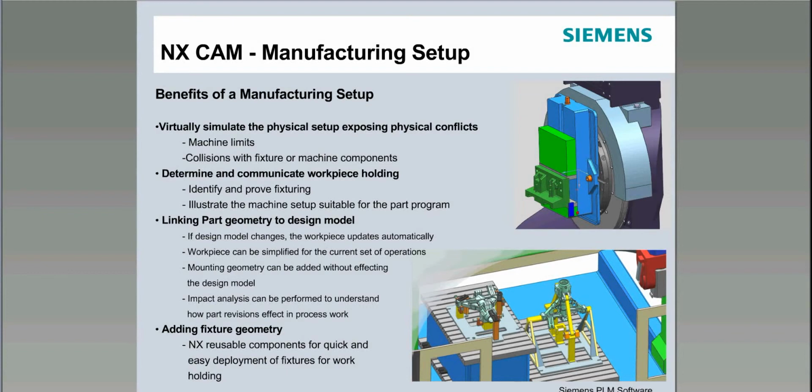Of course, if we've over-machined the part, we can then determine how much over-machining we've done and decide whether or not the part can be welded up, or whether we need to create an insert or start off with another blank piece of material.